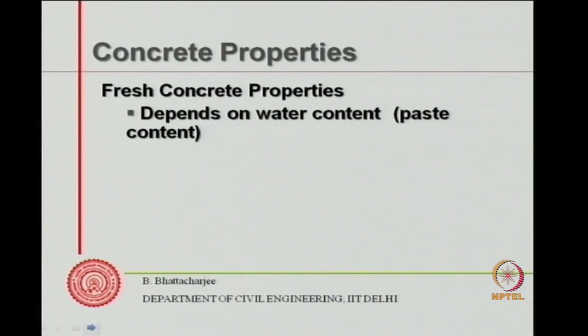How can I mold? The molding process involves essentially driving out the air from the concrete, because fresh concrete when I place it contains about 30% air voids. Normal concrete will contain around 30% air voids, and this has to be driven away. Then the second issue is that seldom is it in the location where it finally has to be, in the shape of the mold itself.